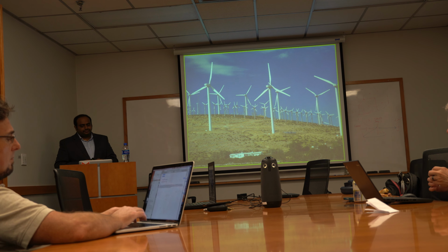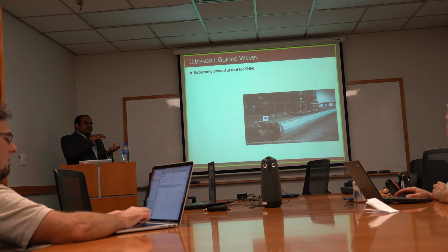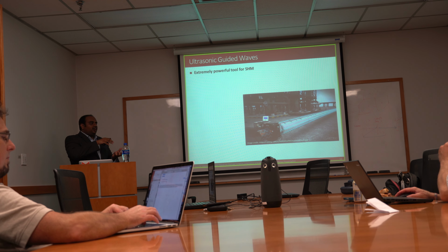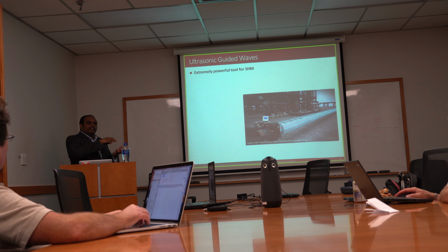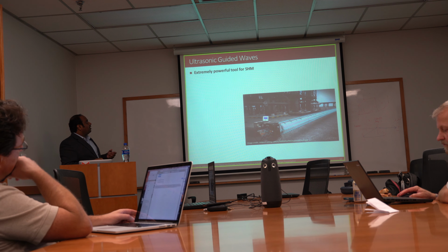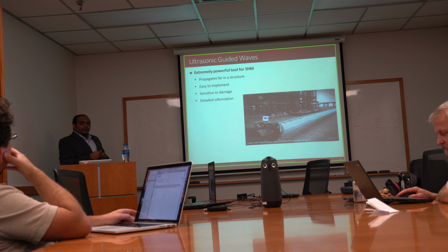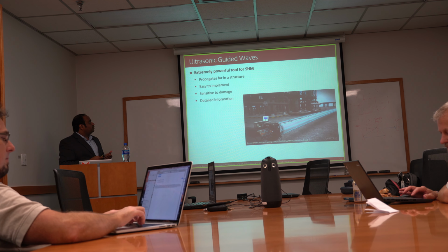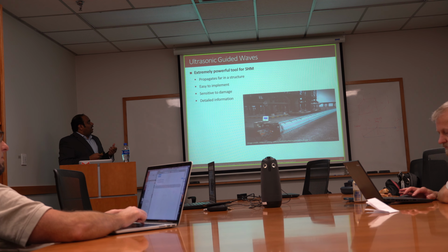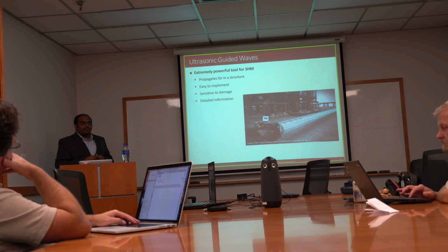So basically, how do we obtain data from these structures? One such method is using ultrasonic guided waves. These guided waves propagate through the structure, and the structure itself guides these waves. That's why they are called guided waves. And in thin plates, these are called plate waves or Lamb waves. We use these because they are extremely powerful: they propagate very far in the structure, and also they're very easy to implement. Another extremely important reason is that they are sensitive to damage.